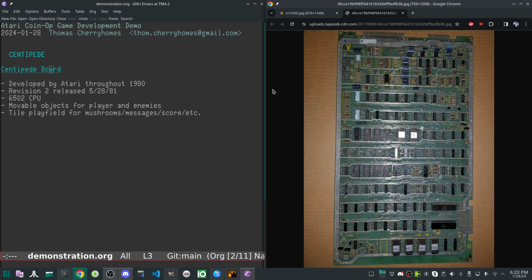It has connections for power, connections to go to the monitor in the arcade cabinet, to the joysticks and various controls and buttons, and it also has everything that you would expect from a microprocessor-based machine, including a microprocessor, programmable interface adapter for input and output, and a number of ROMs you can see both here in the middle of the board and on the edge of the board to contain not only the program code, but also the picture data as well. We will be modifying some of the code in the code ROM.